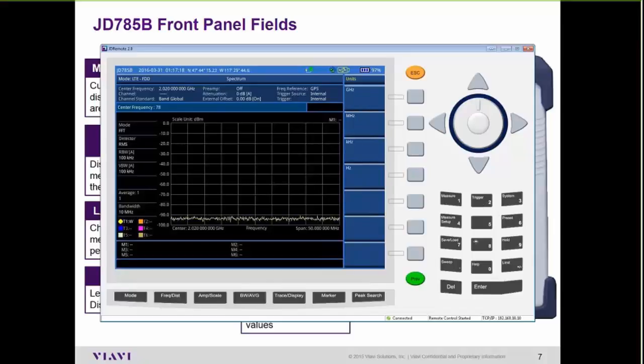Yeah, let's do 751. That's a downlink signal. And again, it does show up here with the little box. So once I press the frequency button here, it brings up the entry box, and so then the numeric keypad takes over the hotkeys. So once I enter that in, I can select my unit.